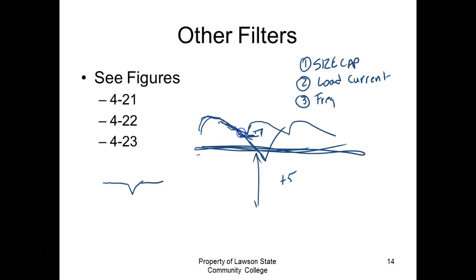So as long as I'm running up and down hills like this, we have no problem, right? But if I get to that hill and it causes that thing to discharge, and it gets down in there, then we go out of regulation. Our output voltage would actually drop down, because instead of being 5 volts, it's going to be some type of average, right?